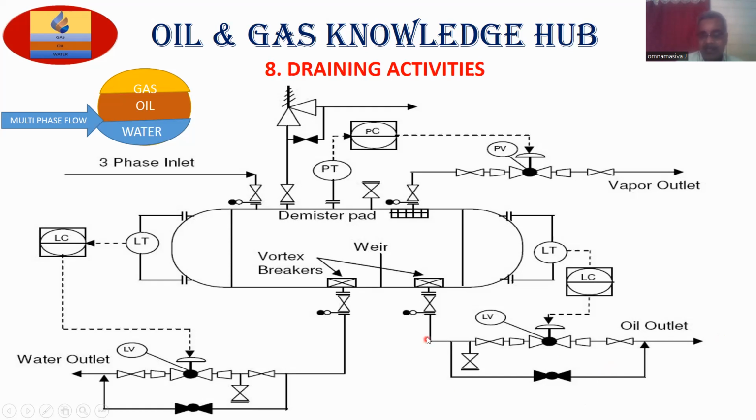Now, this is the outlet. You are going to drain the pyrophoric material from this bottom. Close this valve, open this valve, and open this valve. Make a loop here. Give pressure, flush it out. All pyrophoric material will come down from here. You should place a half-cut drum over here. You should open only opposite flanges in this case. Suppose you are opening a horizontal valve like this, then you have to open the bottom stud bolts only, for draining purpose.